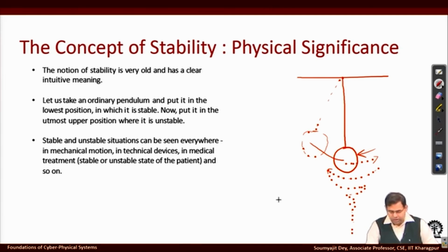This thing entirely is happening due to two reasons. You gave a force here, U, and then the system started moving with that force, but its movement got controlled by the gravitational force, right? And due to that, it was giving this oscillatory behavior. So when we say by intuition that the system is stable, what we mean is it has a default target position. Let's say this angle is theta, and the target position is theta equal to 0 degree, or let's say 0 rad. And unless you are continuously applying some disturbance or external force, this is its stable position.